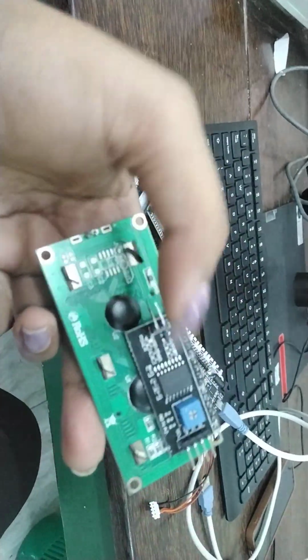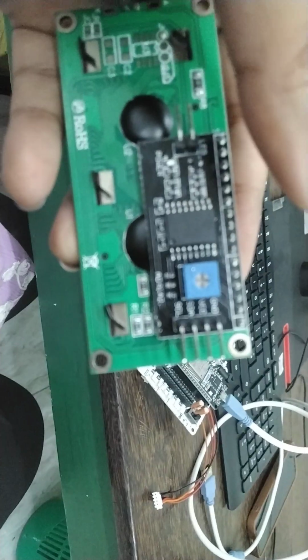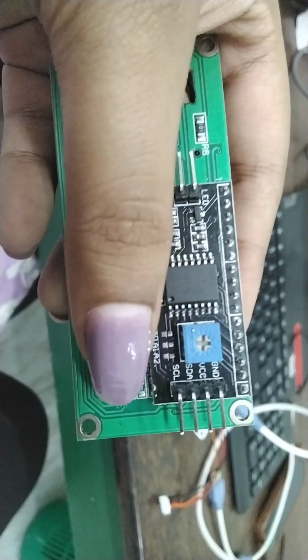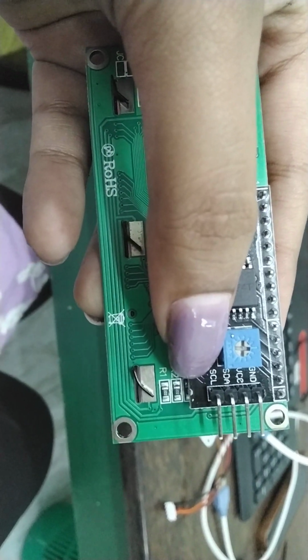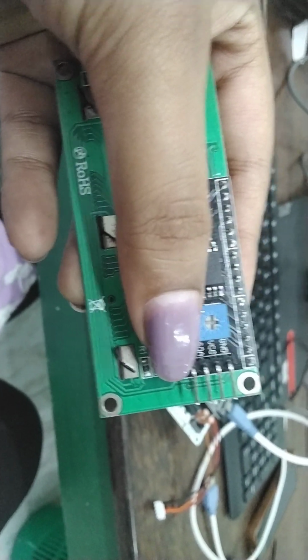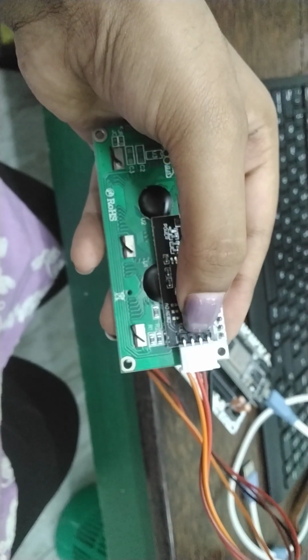And for the next part, we look at our LCD. Here we have our LCD, and here we have the 4 connecting parts. As you can see, we have GND, VCC, SDA, SCL. All of these are written on the side over here, and we have these 4 pins. So we're going to take the jumper wire and we're going to connect it over here. And here is our wire that we have, and we're going to connect it. So this is how it looks once we have connected the jumper wires over here.